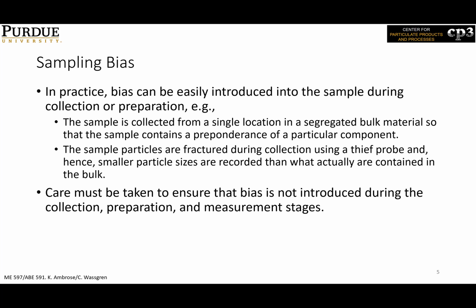In general, bulk powder with small particles may have smaller extraction errors but may have larger sample preparation errors. But for powder with large particles, the extraction error could be higher with a smaller sample preparation error. But the effect of particle size will depend on the particle size distribution and the range of particles that you have in the mix.